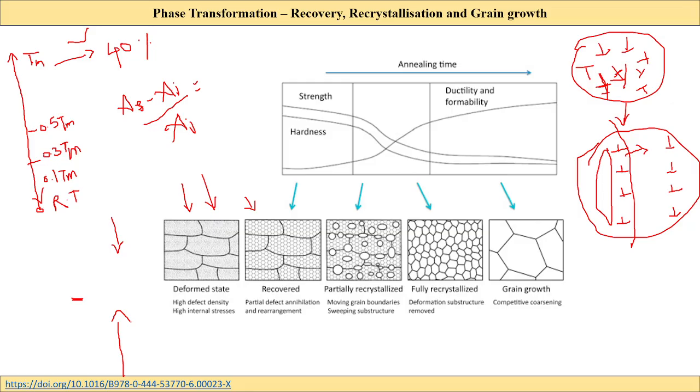So that is the annihilation of dislocation. This partial recovery by annihilation of dislocation is quite low, because finding two opposite sense dislocations is, I shouldn't say rare, but it does not happen very frequently inside the material, right? So it is low when compared to normal recovery.